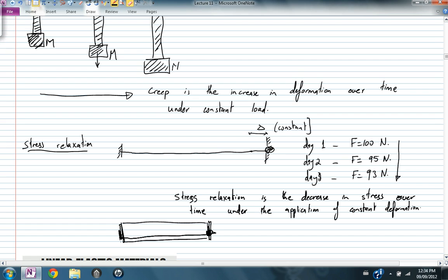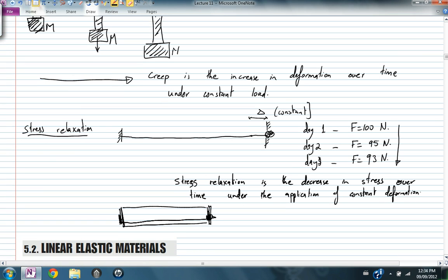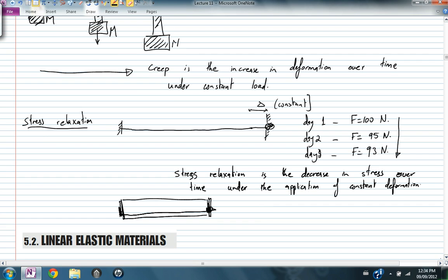And so you want to make sure that 5 days or 10 days or 100 days from now, the force that you designed this concrete beam on is still there, or you want to consider that this force might decrease, and so you need to understand the behavior of the steel due to stress relaxation.